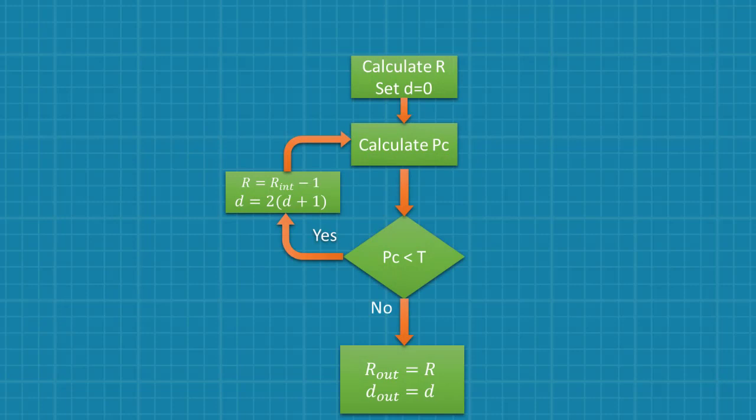In algorithm 1, the target coverage probability is achieved by increasing the separation distance using the SD method until the probability of coverage reaches the target value. Then the new coverage radius is calculated. While in algorithm 2, the target coverage probability is achieved by incrementing the frequency reuse number zeta using the FR method until the probability reaches the target value.